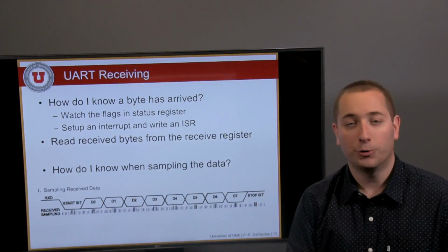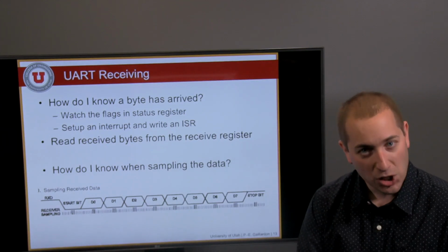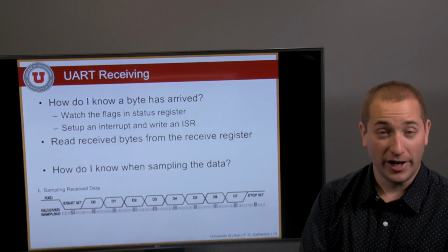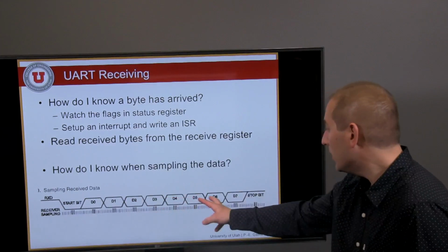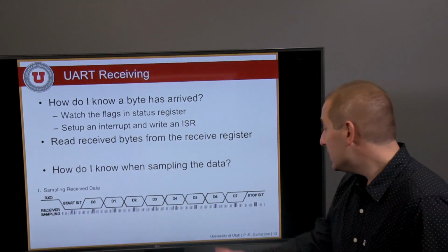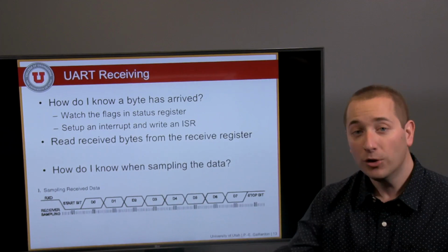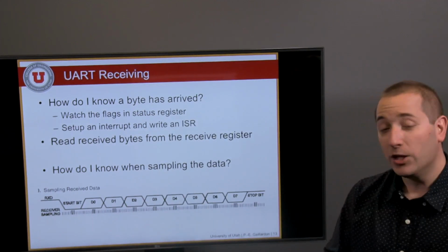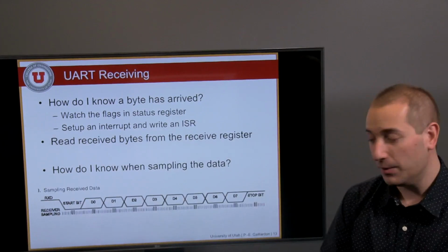How does a UART receiver work? As I said, it's a fully asynchronous communication, which means that no clock is provided. If no clock is provided, my data will be coming at a fixed time interval that depends on the baud rate. However, I still need to resynchronize the phase of my internal clock between the receiver and the transmitter. In order to do that, the main principle is to use oversampling.